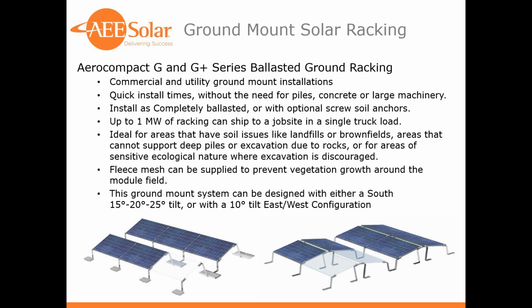So it installs as a completely ballasted system. They also have optional screw anchors if needed, and we've seen a lot of people using those as well. We can ship up to 1 megawatt of racking on a single truckload for a site. And if there's a brownfield or a landfill that can't be dug into, it's really nice there. We didn't think this would be a residential offering, but we're doing a lot of small residential systems with this as well. There's a ground covering, a fleece mesh, that can also be provided to help prevent vegetation growth.